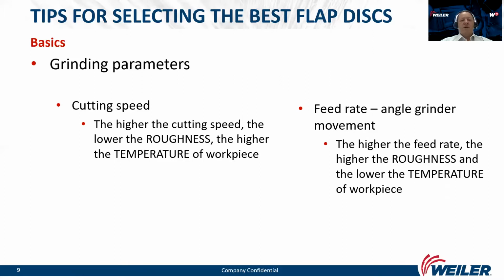So here is very important. If we want to avoid burnings, we have to move an angle grinder fast, and we have to make long movements, especially when we grind welds on thin stainless steel sheets.